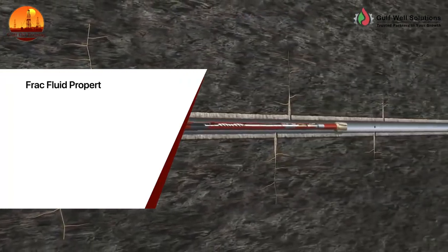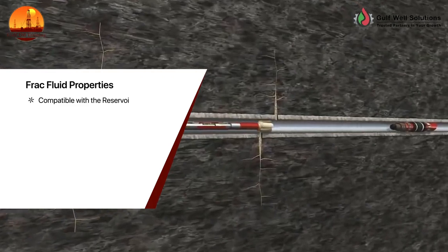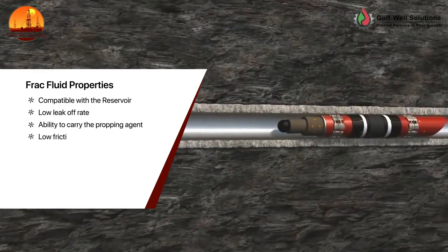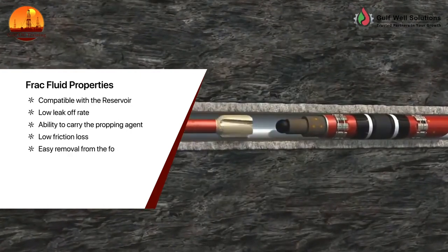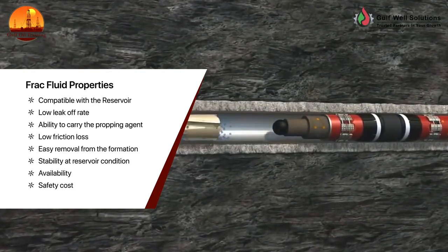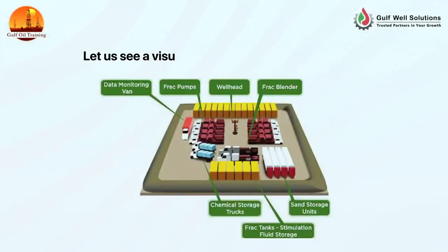Frac fluid properties: compatible with the reservoir, low leak-off rate, ability to carry the propping agent, low friction loss, easy removal from the formation, stability at reservoir conditions, availability, and safety, cost, economics. Let us see a visual illustration of the frac job package setup.